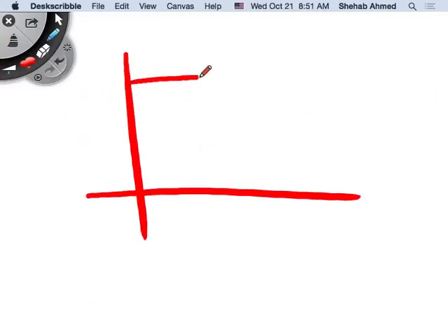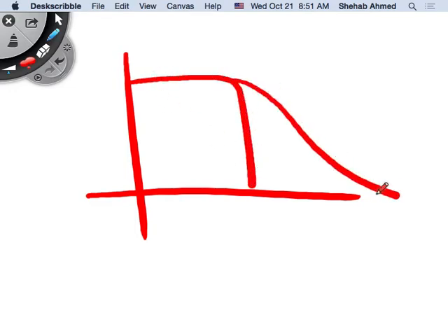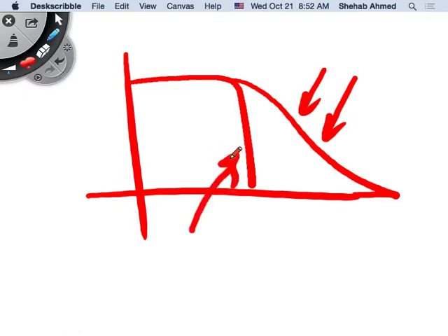The filter bandwidth matters, right? So if your filter looks like this, it's very different than a filter looking like this, right? This filter would definitely allow more harmonic content, right? So it will allow maybe a sharper rise in the waveform like we have here. Not the same thing, because you have a filter, but at least it will allow a sharper rise than this one, for example. This one is eliminating anything beyond 50 hertz. Here, the output would look like a pure sine wave, right? Because there's no average value, and this is eliminating everything beyond 60 hertz.